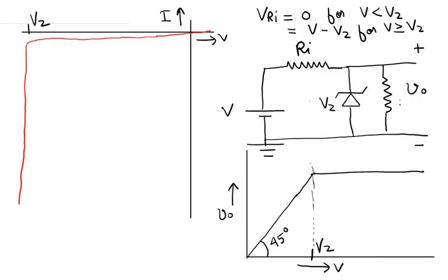Okay, so this is a load resistor RL across which we want a regulated output voltage, and we can connect this RL across this Zener diode to get a regulated output voltage. For example, if I have a circuit which cannot endure a voltage greater than 5 volts, if the voltage across the chip increases to a value greater than 5 volts, then that circuit would become damaged.